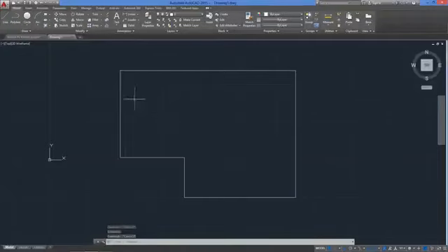Now let's use a command you won't have in the ribbon. Type with the keyboard P-edit and hit enter. With this, we'll transform all of these lines in a single polyline or object. The first prompt is select polyline or, and the other option we have is, as you see down here, multiple. Let's select it by clicking on it or just typing the letter M and hitting enter.